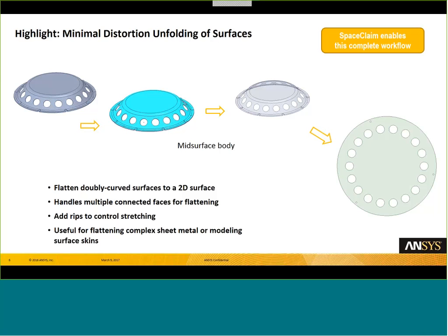But then we said, well, if we're able to wrap things onto it, we should also be able to unwrap. So if you get a doubly curved model, you should be able to unwrap that into its flattened state. That's basically what we're doing here: we're taking surface geometry. Notice this is a little stamped part. We're letting you select on that and unroll that and flatten it back into its flat state. And we really try to minimize the stretch on the area of the geometry, but also the length of edges, so we try to keep them as close as possible to the original shape.